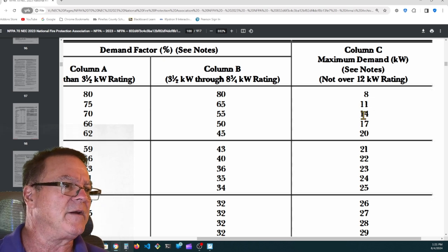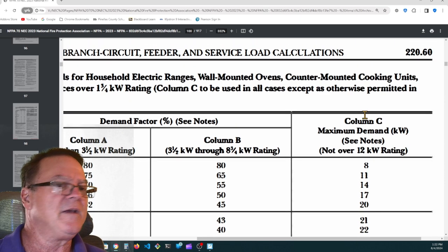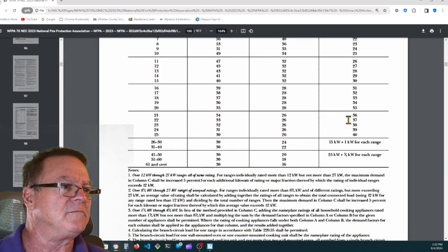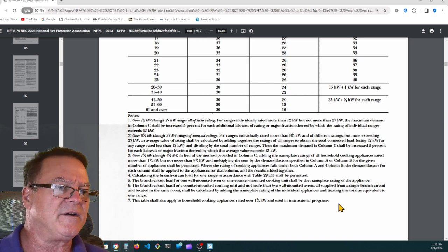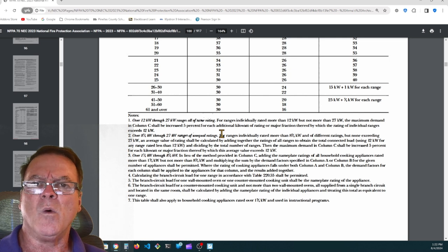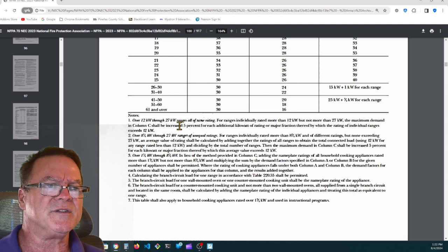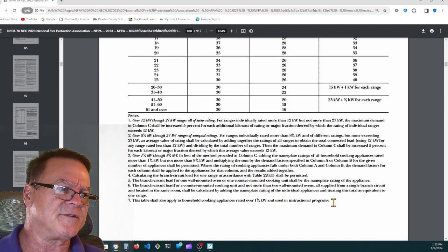All right. Look, there's three of them. That's 36 kW. Three of them, it's less than half, 14 kW. All right, we've looked at that enough. And there's a lot of different notes down here. I'm not going to go over the notes. I think you do this again in 263.01. Then we'll get more in depth as to these cooking equipment demand factors.